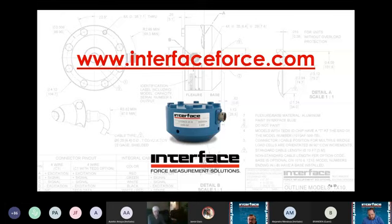Yeah, and speaking of cables and changing temperature, there are many products out there that don't have internal temperature compensation for the bridge, like our Convex BT does. Simply handling the cable can then have a pretty pronounced impact on the signal. So there are a lot of aspects. We talked a lot on the component level today, but there really needs to be a lot of review from a system level standpoint.